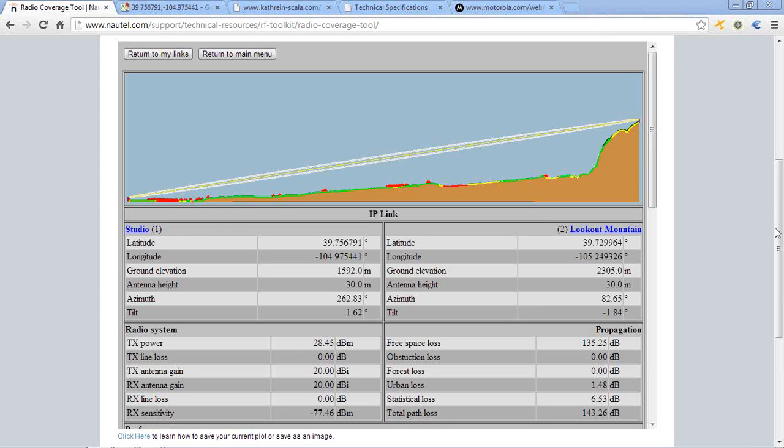Is there a spot to enter transmission line length? If not, how can it be accurate without that parameter? Want to explain how you're estimating transmission line length? Yeah, they are pre-calculated in the program settings, when you select the type of antenna you're using. We also have a pre-selected line loss, and if you change the antenna height, the line loss will increase as well. In other words, it assumes a certain length of feed line based on the height of the tower at the site: the difference between the height above average terrain at the site and the height at the top of the antenna. And we selected the type of coax according to the power level. Yeah, okay. So it's a reasonable approximation.